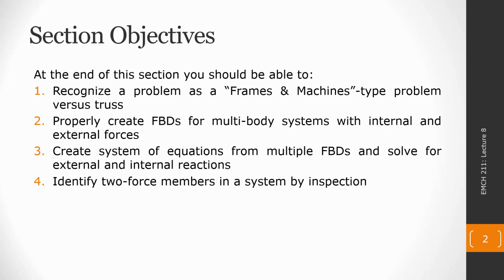You should be able to properly create the multiple free body diagrams for these multi-body systems and correctly place internal and external forces into the free body diagram. From these free body diagrams, you should be able to create a system of linear equations and solve for the external and the internal reactions in the system. And you should be able to identify two force members in the system by inspection.